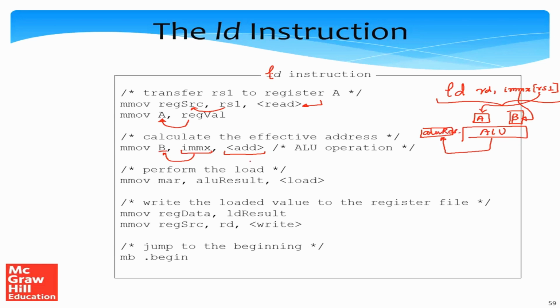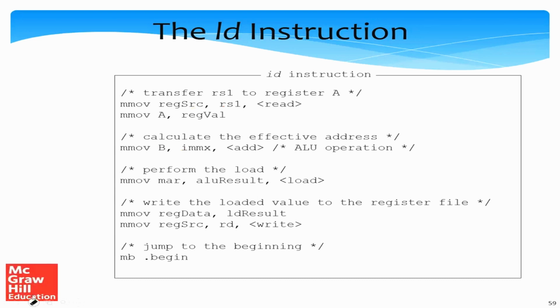So what we will now do is that using the shared bus, we will transfer the address ALU result to the memory unit. So recall that in the memory unit, maybe let me just erase and redraw. Let me erase all of it. So recall that in the memory unit, we have the data memory.